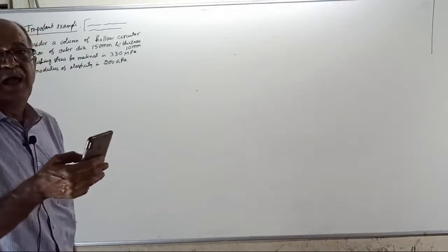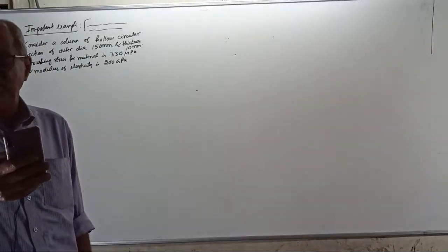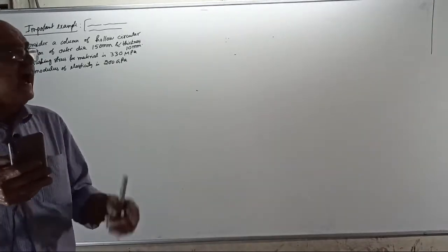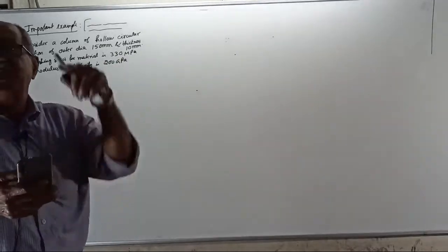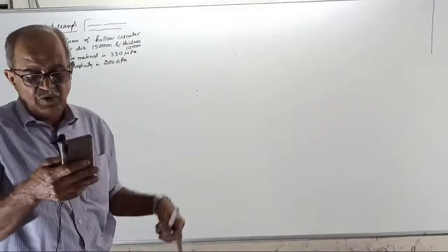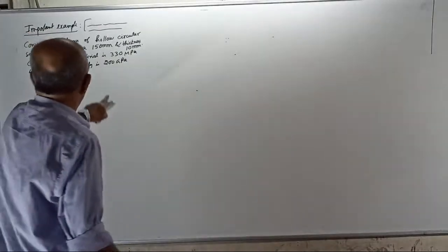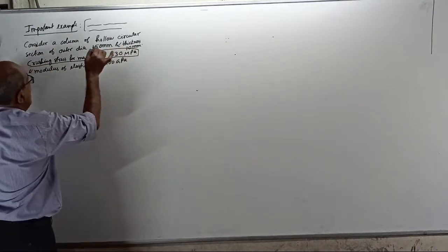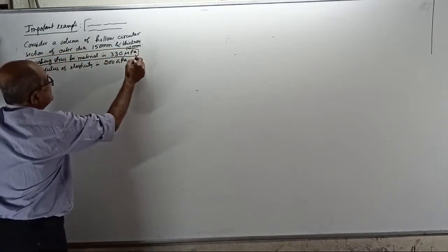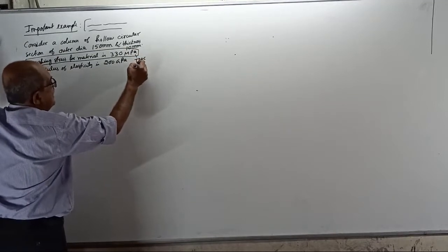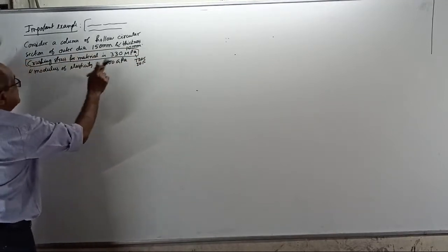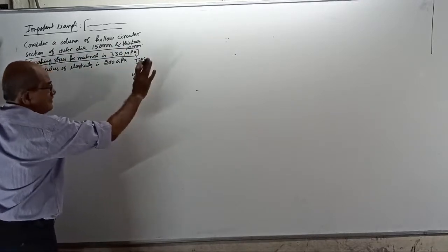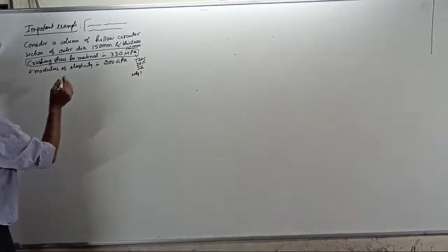When I write a formula, pi square EI by L effective square, that is the original formula, or pi square EA by lambda square. That was covered in the previous class, but that was only not clear, so I will write once again. Crushing stress for the material, remember, does not come in Euler's formula. That's all. Wait for some time. Then, this is the property now.